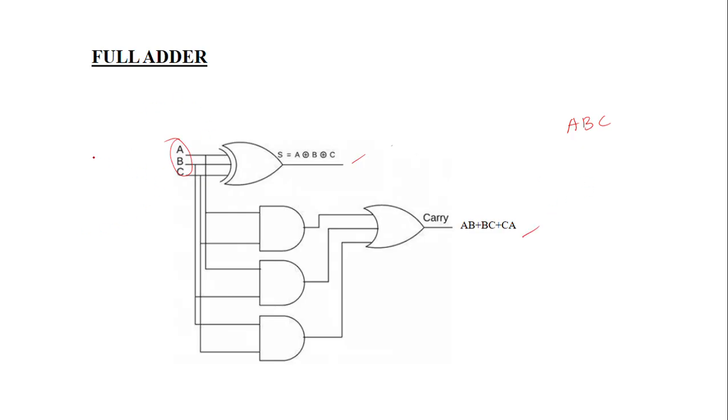A full adder is nothing but our addition operation. In a half adder we can give only 2 inputs, meaning 0 and 1, 1 0 like that. But in real time, there may also be generation of carry. For suppose if the inputs are like this, here we can easily use a half adder, then the sum is 0 and the carry is 1. But here there are 3 inputs, so how will a half adder work? For this purpose, we have to move on to the full adder.